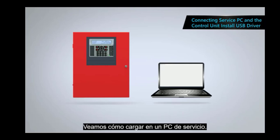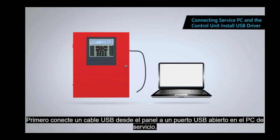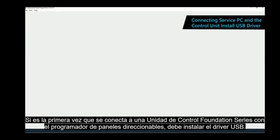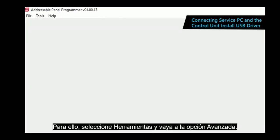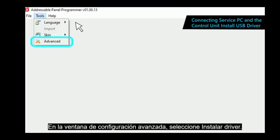Let's look at how to upload to a service PC. First, connect a USB cord from the panel to an open USB port on the service PC. Then, open the addressable panel programmer. If this is the first time connecting to a Foundation Series control unit with the addressable panel programmer, you must install the USB driver. To do so, select Tools and go to the Advanced option. From the Advanced Settings window, select Install Driver.